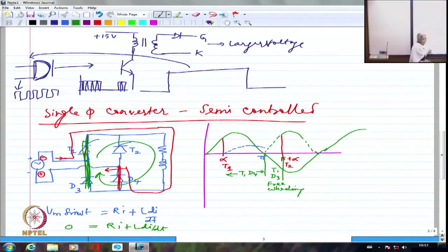Right? So there is nothing which is actually coming up as source voltage. Whereas in the fully controlled converter, because there is a negative portion of the voltage acting like a drain on the inductance stored energy, definitely the current could have fallen faster because it is essentially draining the energy of the inductance. But now the current will not fall as fast.